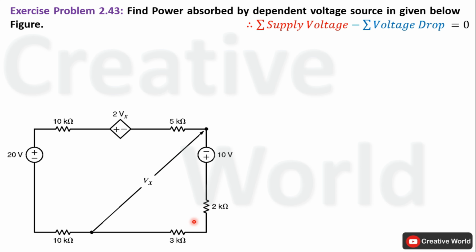Before applying Kirchhoff's voltage law, first we have to identify the current inside this semi-closed loop with its direction. I am assuming the direction of current counterclockwise. You may take clockwise as well. Now, according to the assumed direction of current, make polarity notations across the resistive elements. We will use passive sign convention theory. According to passive sign convention theory, current entering terminals are taken with positive sign and current leaving terminals are taken with negative sign.